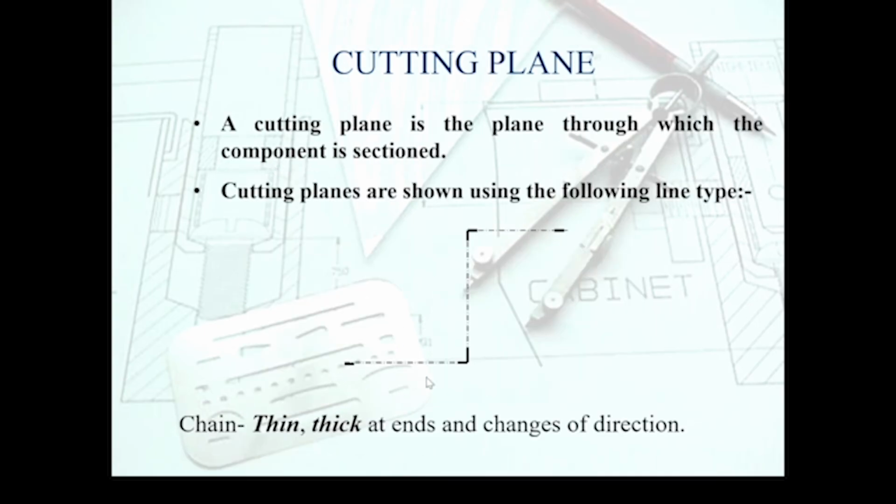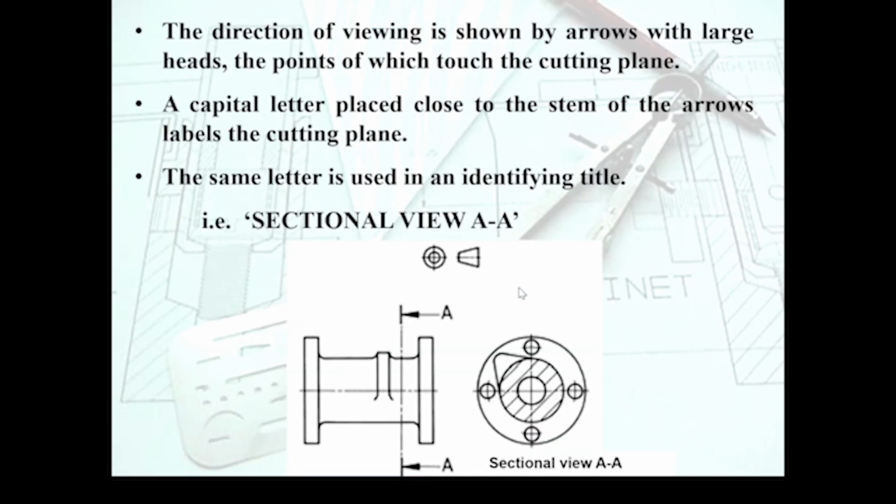And this is probably just as important, to be able to identify your cutting plane. On the technical drawing, you would generally show this kind of a line pattern, which looks very similar to a construction line from SolidWorks. However, it will have some peculiar turning points and the stopping point when produced, and this is called a cutting plane. This indicates the point where you are assuming the part has been cut open, and then you are allowed to reveal the details of the part on the inside.